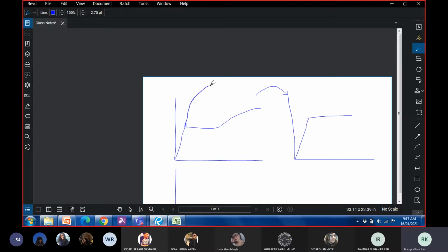So this curve would be something like this, in which there is no well-defined yield point as we have in case of mild steel. Okay, but one thing that we've seen before, and just to reiterate it, is that these two curves overlap in the linear elastic region, and then the high strength steel curve goes higher because it has higher yield strength.